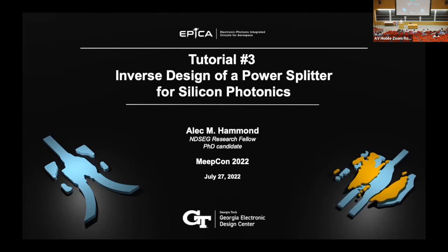Yeah, so this kind of relates to what we were talking about earlier, right? You could window your response in some way to try to get some sort of structure at the end of the day. I think a better approach would be what I was talking about earlier, where you use a Padé approximation or some other approximation, such that you only have to simulate for a brief span, and then you get the analytic form of the signal at the end of the day, and you don't have to wait for it to ring out. There are some downsides to that because now you have to store your data not just at every point in space, but at every point in time, so that you can create those fits.